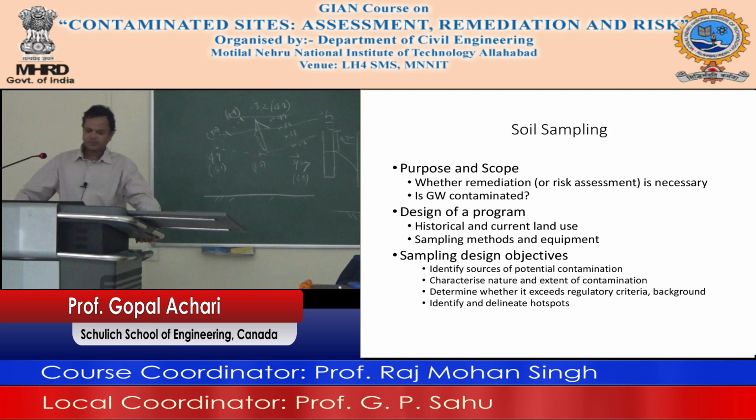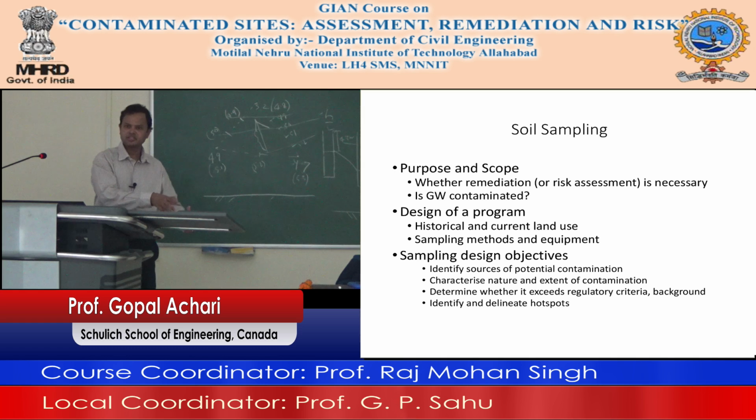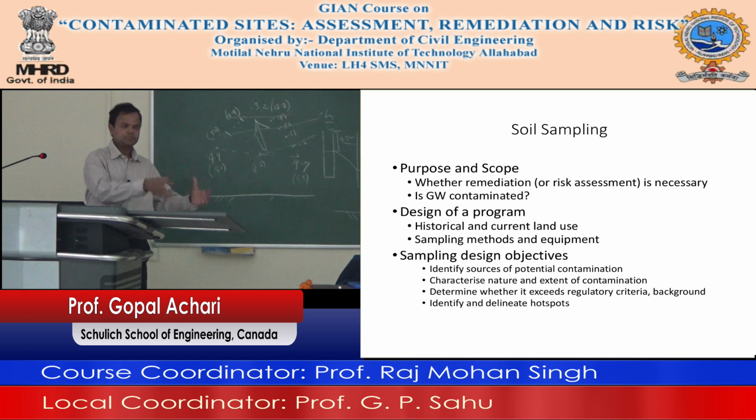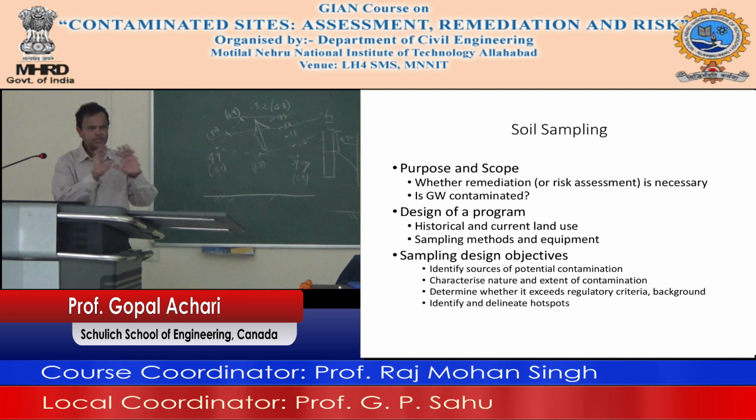You should identify and delineate hotspots. You know what a hotspot is? It is where you find high concentrations. In a large area, you may find very high concentration of certain things in certain locations because there were some activities that went on there. Okay, that's a hotspot. So delineate the hotspot. Find what are the limits of the hotspot, because you don't want to clean up the whole site, just the areas that require cleaning.